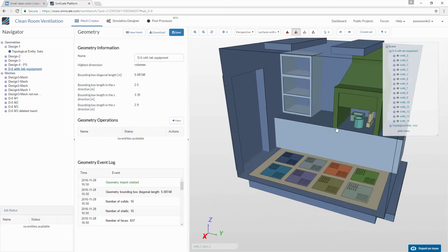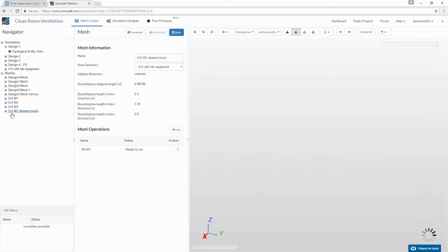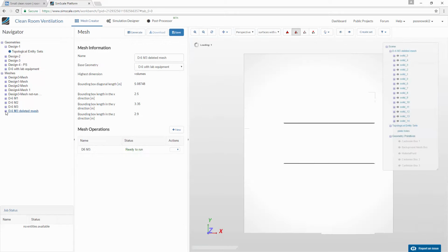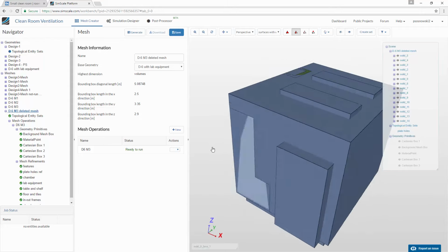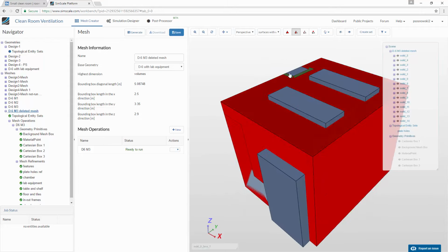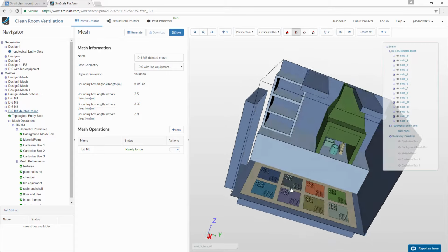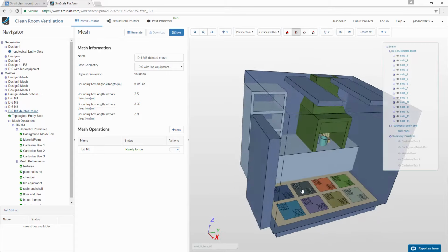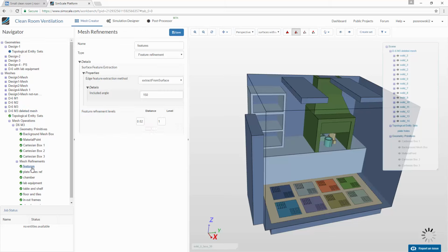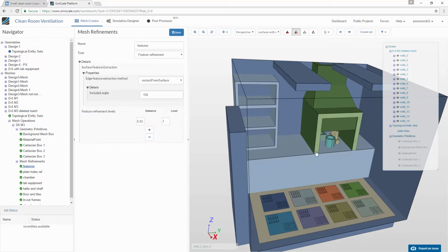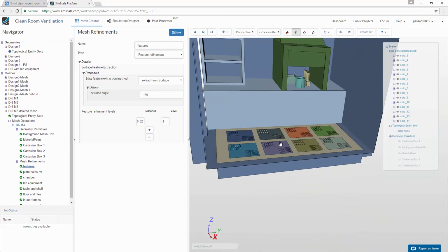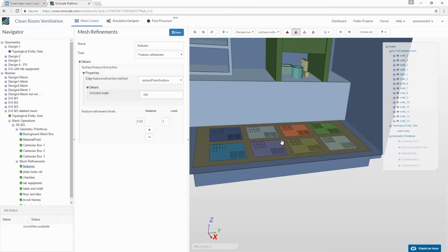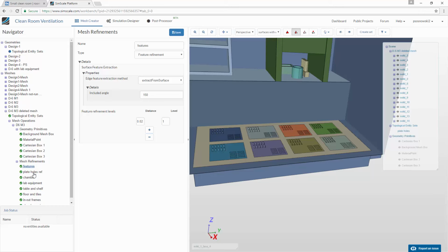I will not go directly into details of the way that the mesh was created. We will simply talk about the possible refinements that may be helpful in order to get a better performance of our simulation. First of all, we will need to make sure that all the features of the flow are properly resolved. So every line that is present in this CAD will get an additional level of refinement, splitting the base mesh that is being created, the very coarse mesh, into two.